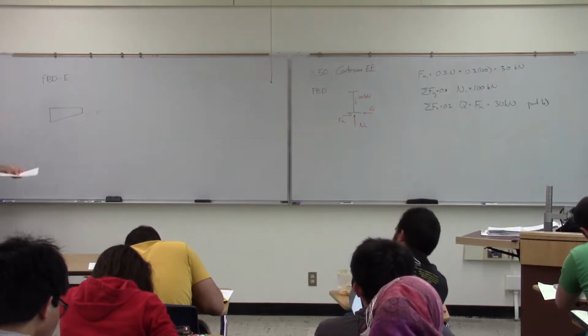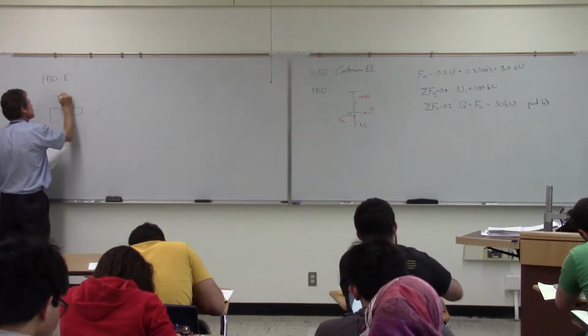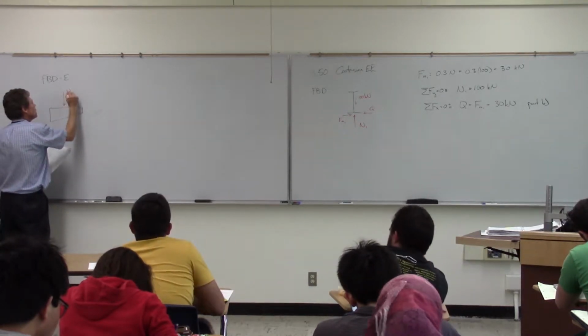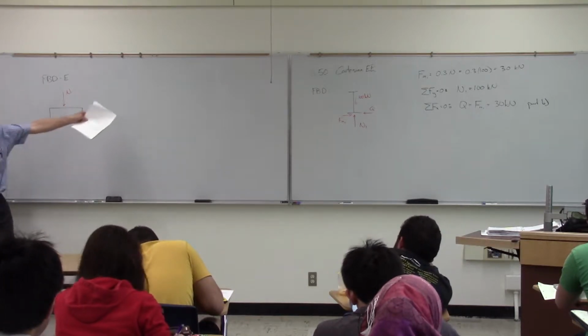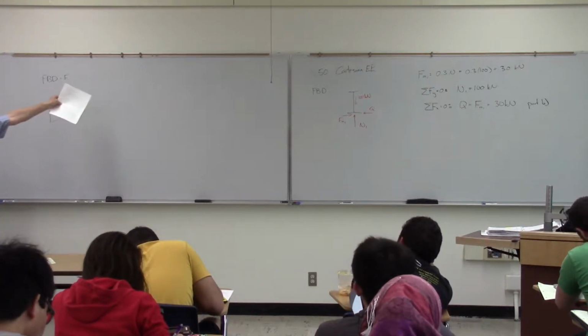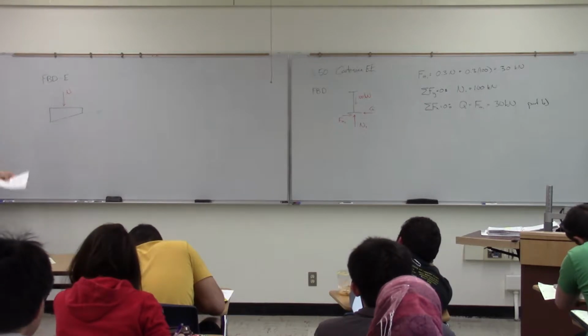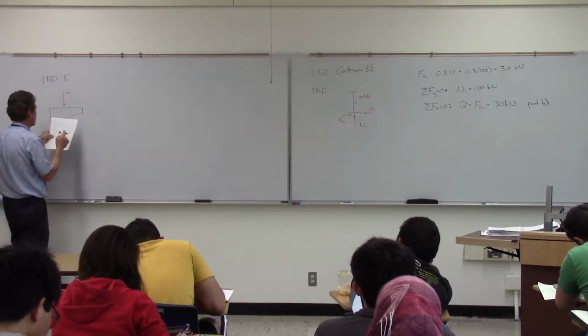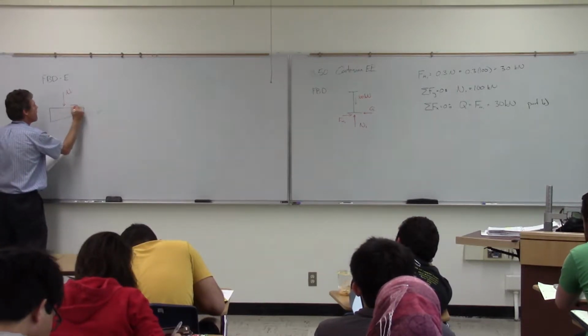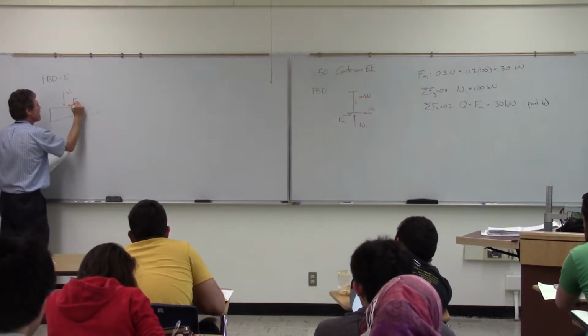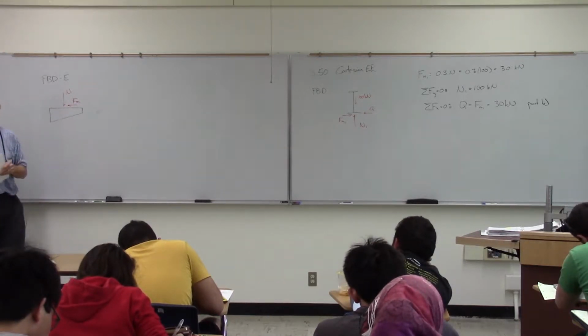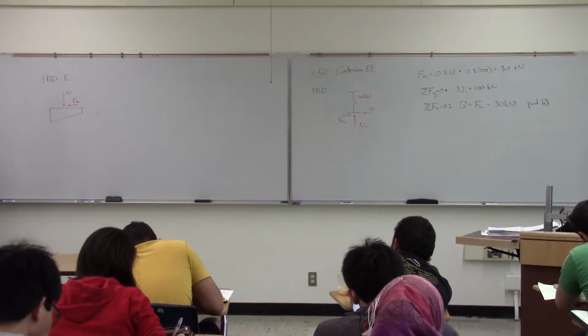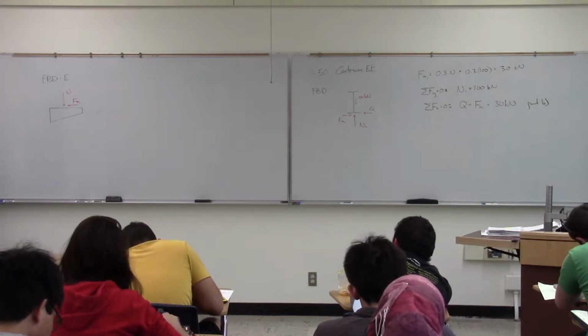This is a machine, so we're going to be taking our forces that are known and putting them in an opposite sense. So we solve for N1 over there, and it came out positive, so it was going up on that one. It'll be pushing down on that one. And my FM1 will be acting in that sense, opposite of what I've got on that particular free body diagram.